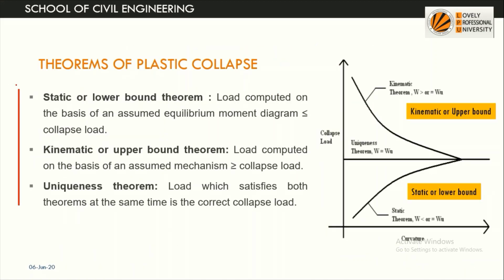Now we'll come to an important point, that is the theorem of plastic collapse. We know that in plastic analysis, MP is the moment that corresponds to formation of a plastic hinge, and once a sufficient number of plastic hinges are formed, the structure will be converted into a mechanism and the structure will eventually collapse. Corresponding to this value of MP, the load will be referred to as the collapse load.